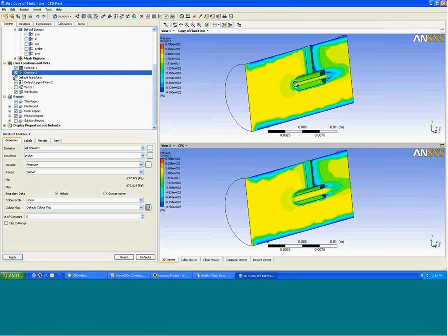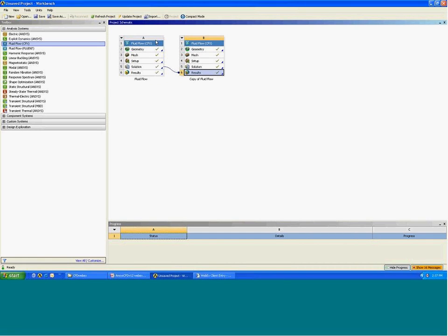So in 12, based on the architecture and program schema, it is very convenient to create a sequence of design iterations. Based on this situation, you can easily perform a sequence of design-level CFD analyses. Once your baseline case is established, if I exit out of Post for a second and go back to the project page, once your baseline analysis is established, you can go through geometry variations as well as flow variations, and address the design and the performance of each one of the conditions.